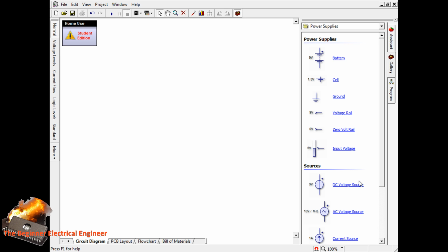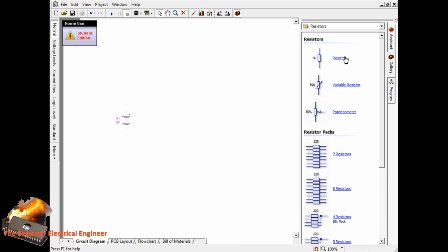Now let's just do an example, because JHS open source has asked what Kirchhoff's voltage and current laws are. Let's just use a battery here and let's get some resistors. Well, Kirchhoff's voltage law is actually quite simple. It's basically saying that the voltage of a power supply is shared among each of its resistors, and the easiest example of this is literally just 3 resistors in series hooked up to a battery.